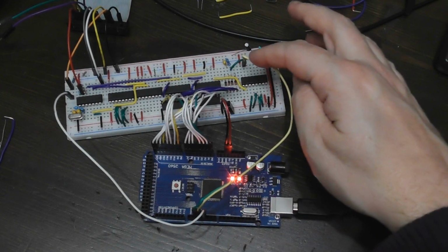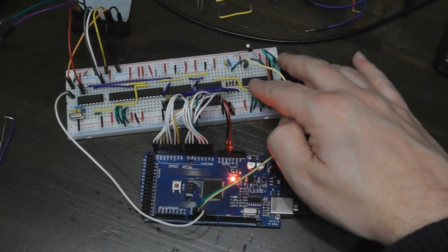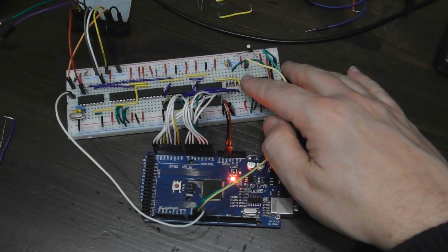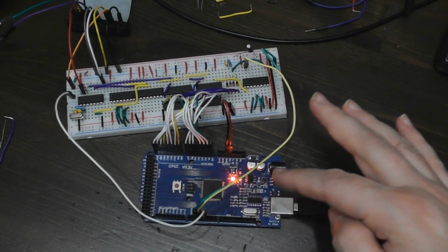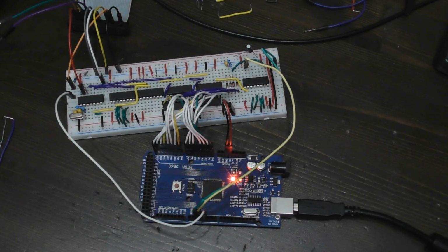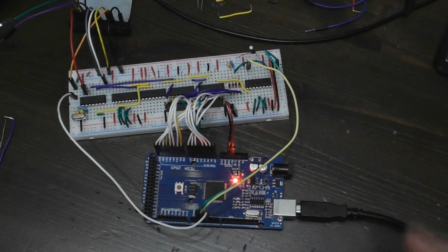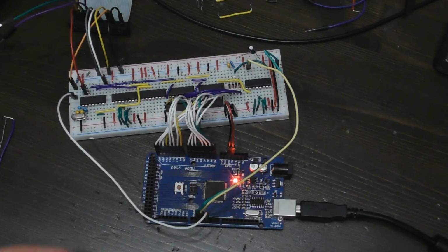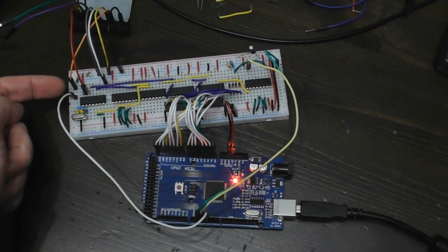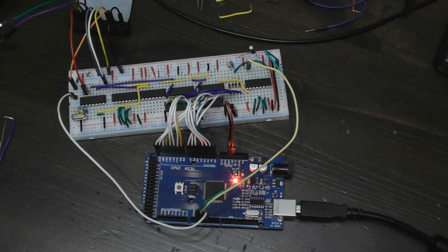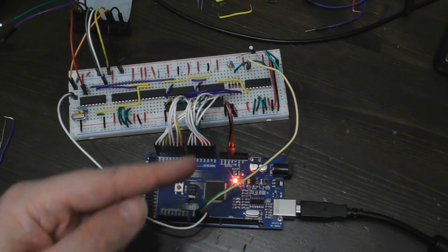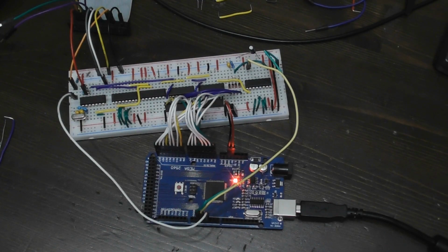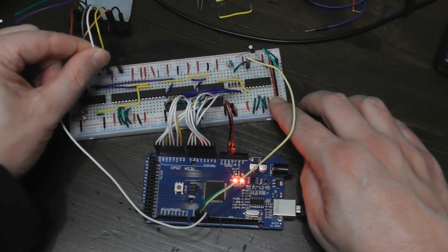The Arduino is hooked up to the terminal count output from this counter on pin 15 there, and that's taking the place of what was the clock before in the Arduino code. So that goes high once per byte and triggers the Arduino to actually read the data from the shift registers. The white wire is still connected to the index signal from the disk drive so that it can tell when the index hole passes, and the green wire here is not really doing anything anymore. It's not actually connected at that end. So that's the hookup for the Arduino. The disk drive hookup's of course exactly the same as before, and the hope here was just that it would be more reliable. So let's turn on the disk drive and see that running.